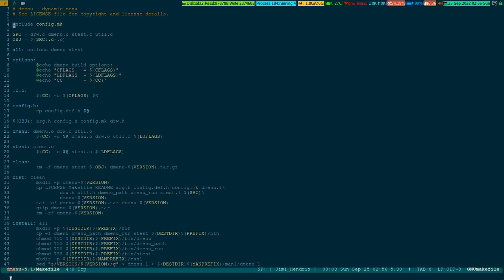Okay, so you can see you can include another configuration file inside the Makefile like this. As you saw, it declares two variables and it is expecting this file to be present in that directory. You can see it assigned the object file like this, which comes out of the .c file. Okay, what I've shown you. So if you do all, it will take this dependency with it. These targets are built depending on this kind of stuff.